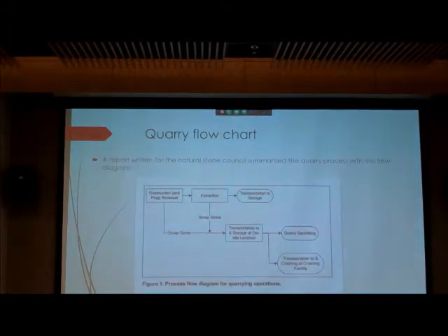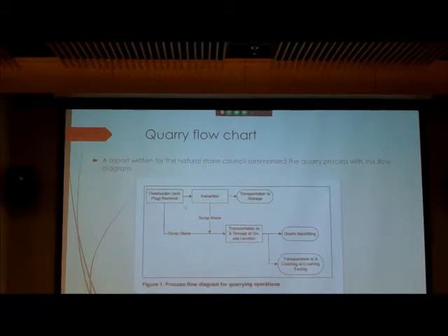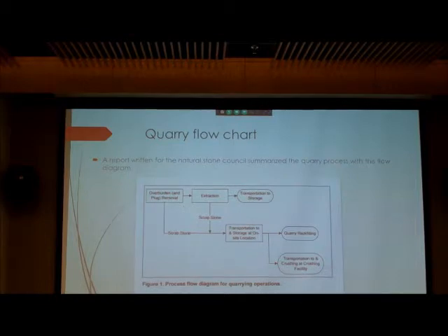Okay, so here is how a typical quarry works. First, when they pick their site, they find a lot of rocks that they like. Then you have to remove what's called overburden and plug. Overburden is dirt or vegetation and rocks, not of the kind that you want, that you have to pull off the top. So it's a lot of digging in to find the rock that you are wanting to quarry. And then plug is the rock you want, but it's the bad parts of that rock. It's not commercial quality.